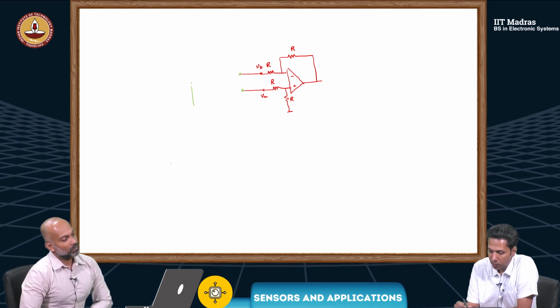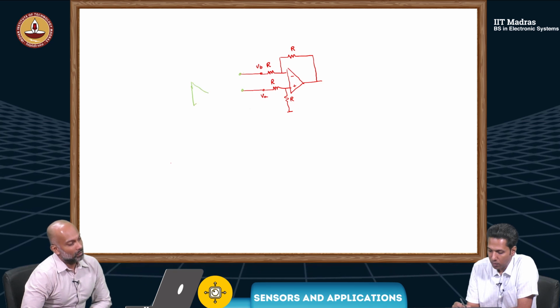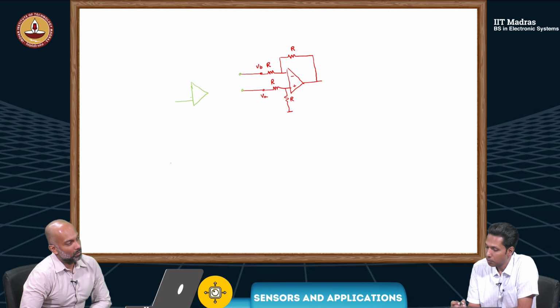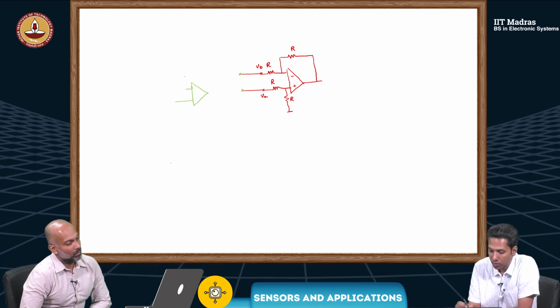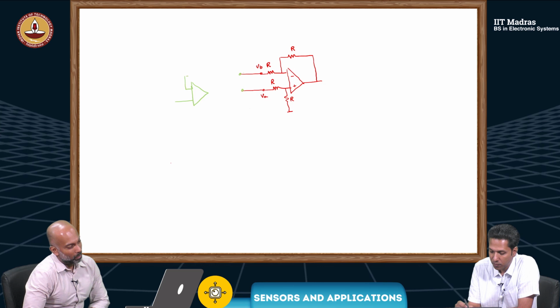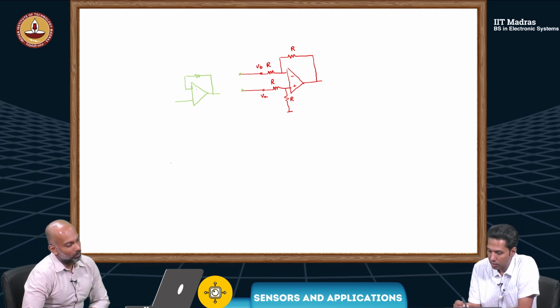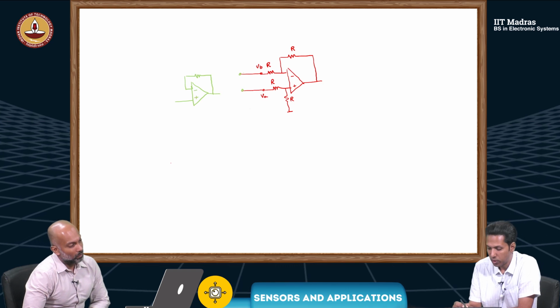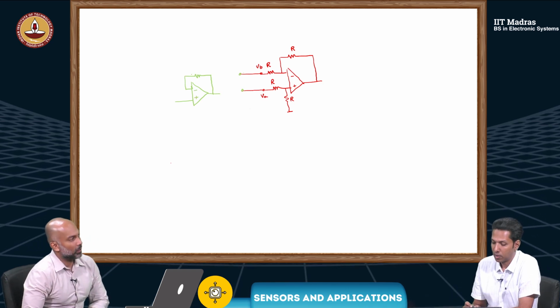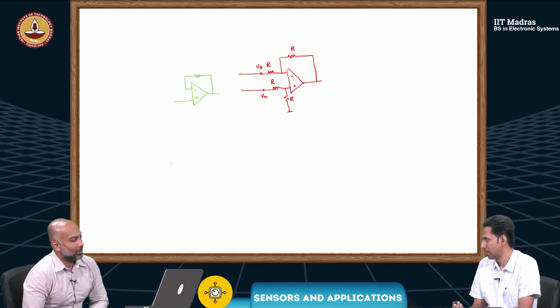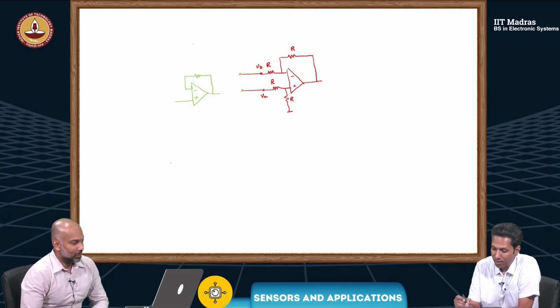Let's say we are going to just modify this buffer circuit that we have drawn. Let's say in the buffer, or the voltage follower, I introduced a resistor here in the feedback. No effect, because anyway, there is no current through that.